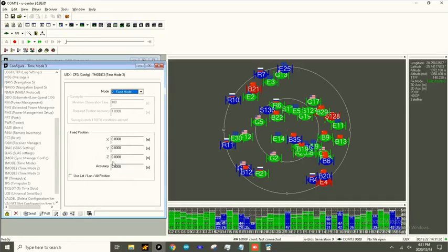now that we know where that receiver is. Let's say, for example, we want even greater accuracy of the receiver. 1 meter is not good enough for your application. Then we can start recording raw data received from the receiver and send that to a third party for post-processing. So this recording of data typically occurs over quite a longer span of time than the few minutes that we just demonstrated, typically anywhere from 2 to 24 hours if we want that sub-centimeter accuracy.